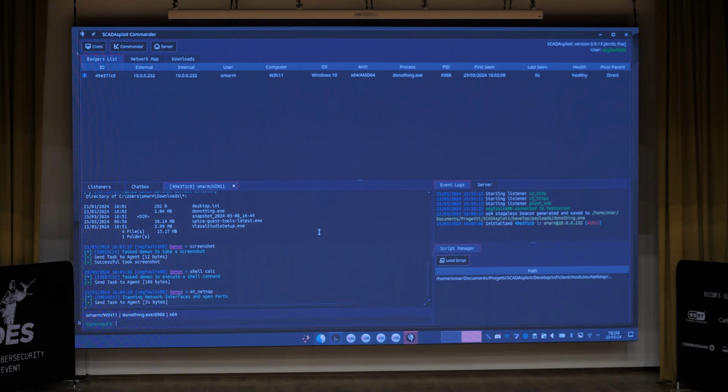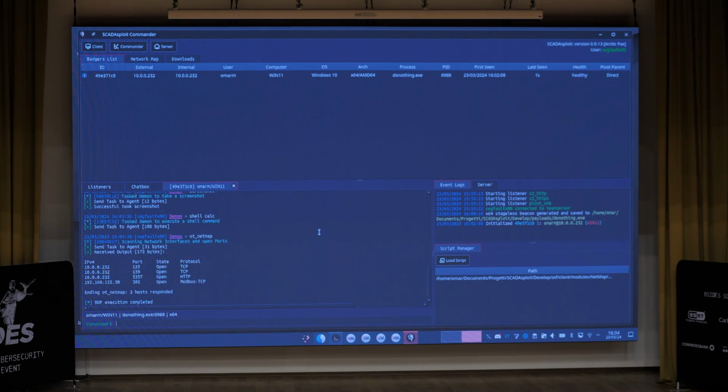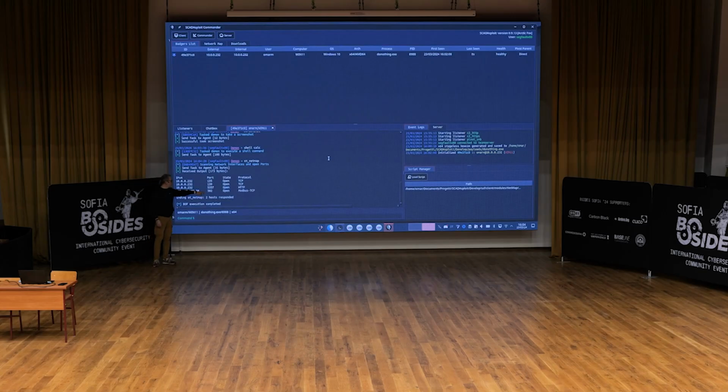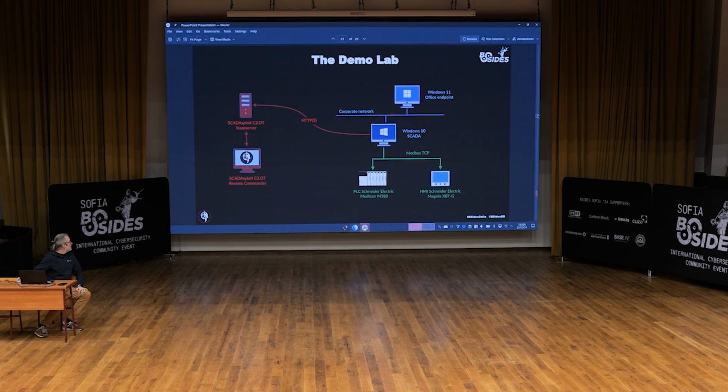It's a command that tries to discover all the possible interfaces inside the computer. And we find another network interface that is here that uses port 502. Port 502 is used for the Modbus TCP protocol. Oh, good. So we have the first information related to our infrastructure. Why? Because we are here. We have the first connection to the IT level, and then we have the second network interface to the OT level. Good, funny.